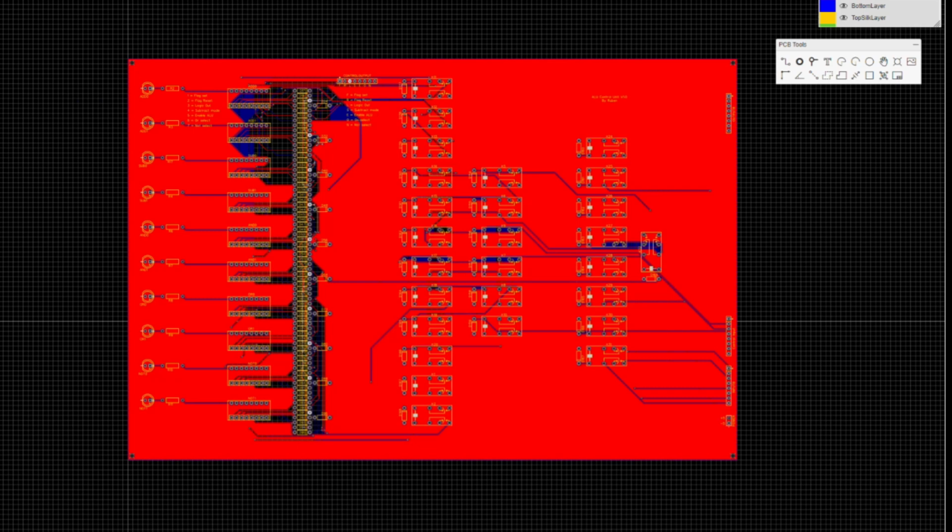So this is the ALU control unit. This will control everything in the ALU based on the input word that comes in here, or the control input. This is a 3-bit number which tells it if it's an add, subtract, an AND, an OR or a NOT. You have an extra bit which is which clock pulse we're on, if we're on the first or second part of the execution cycle, that goes at the beginning of this decoder.